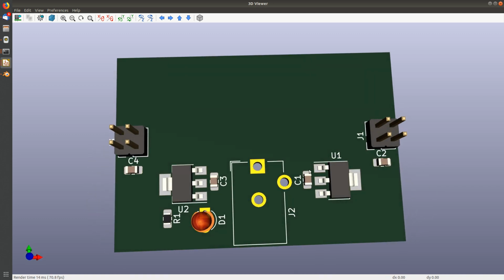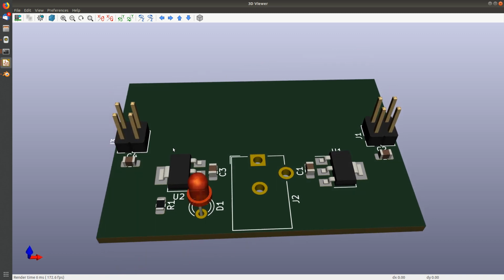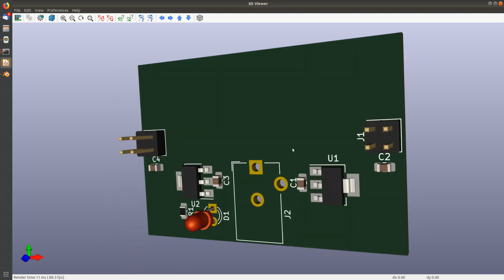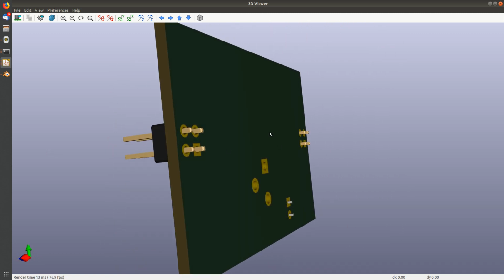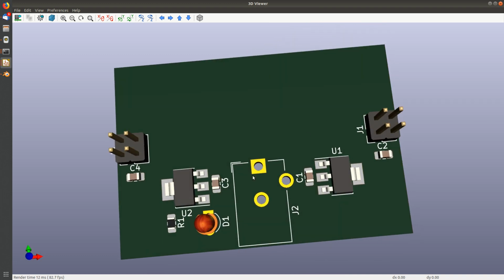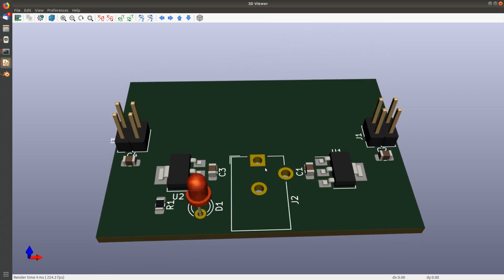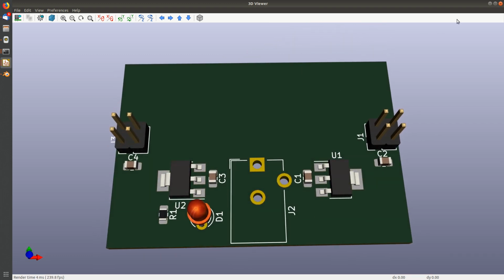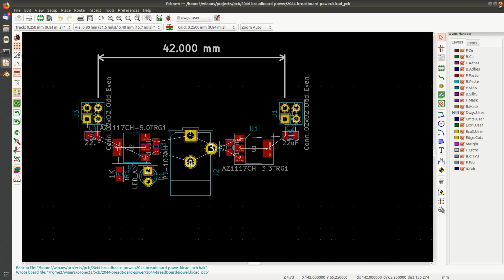So one thing that's weird, other than the board being too big, these connectors are facing the wrong way. Now, you know and I know that you can just as easily flip it over and solder it sticking down instead of up, and this would be okay, but it's not very high quality to do this. So what we want to do is flip them over to the other side of the PC board.